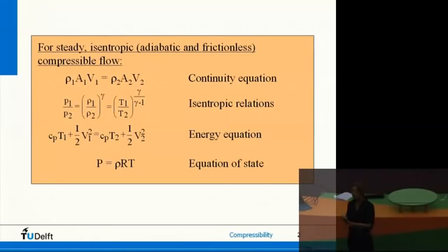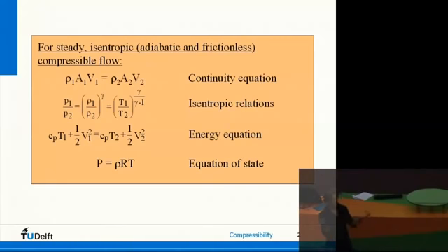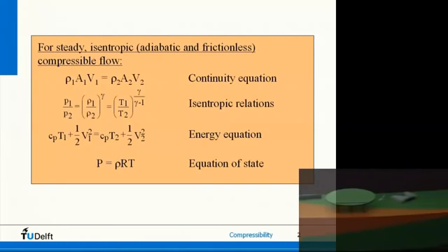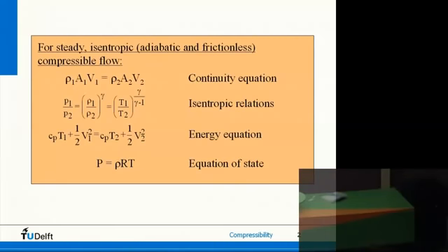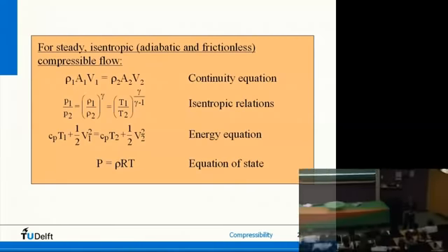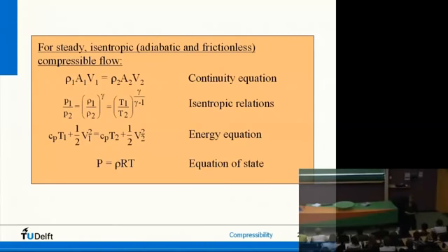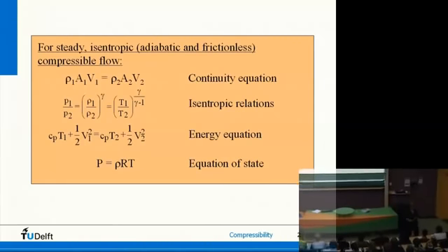Actually, if your flow is fast, supersonic, transonic, you have pressure and density changes such that the temperature does change in your flow. So through P is rho RT, it can expand very much, so the density can drop a lot, and then something will happen to the temperature as well. So please bear in mind, isentropic flow means there's no heat added or subtracted, but the temperature can change. And the other thing is that it should be reversible so that dissipative effects can be neglected.